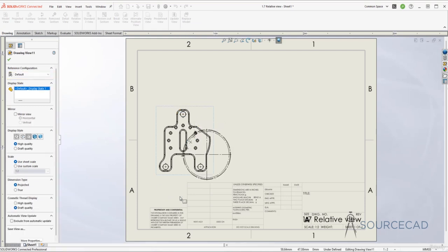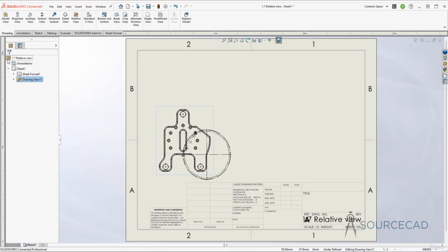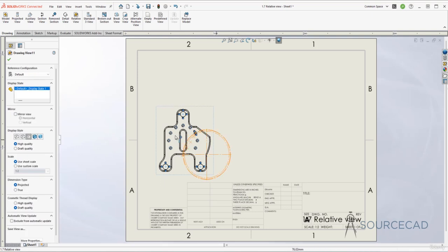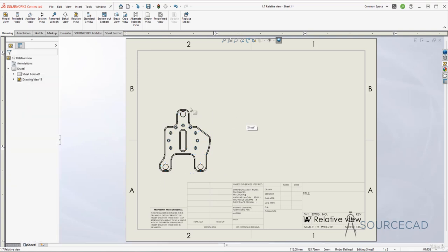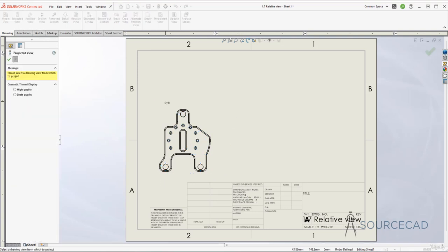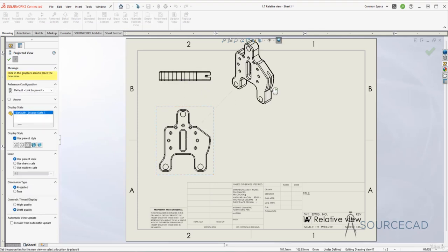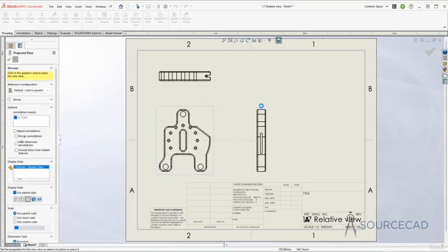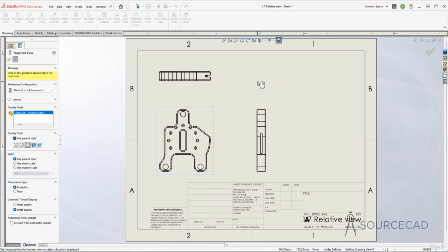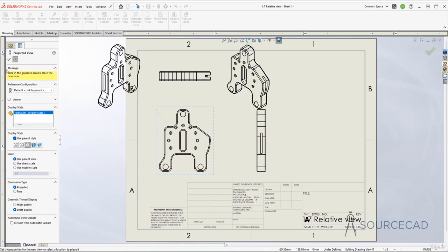And that's our primary view. Now, once the primary view is added, you can use all the projected views and you can just add it in your drawing. Before I do that, I'll, however, just delete all of these construction geometries. And now we can go to projected view, select this drawing and just click here and to different locations to just create all the projected views. So here I'll maybe just create 3 of these views and just click OK.